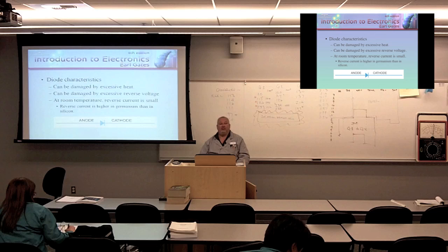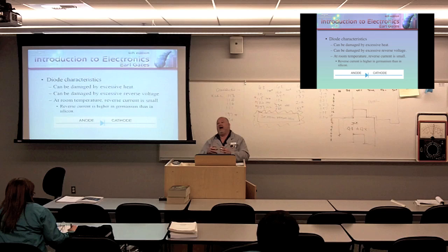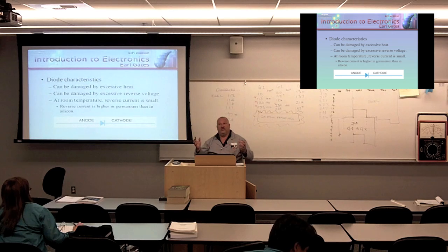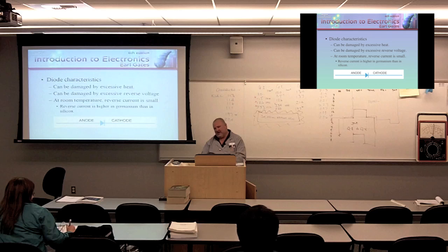You build an electronic project and you think you're going to put a bunch of diodes or solid-state devices inside a sealed box and expect them to do wonderful things with high power. Well, unless you provide adequate cooling and airflow, heat is going to build up, and eventually it's going to explode and fail catastrophically.